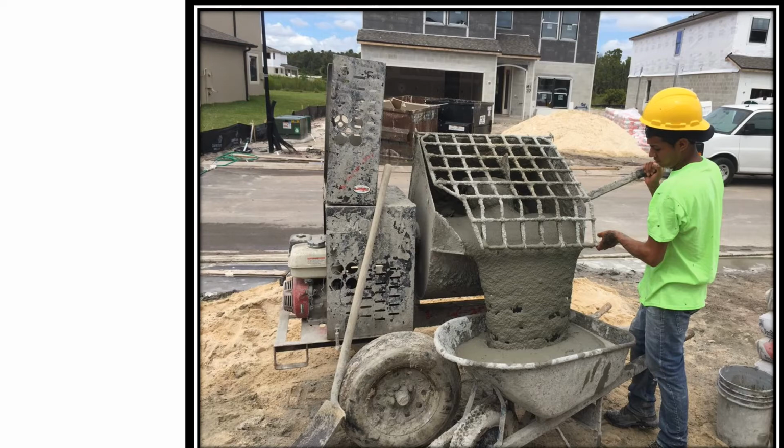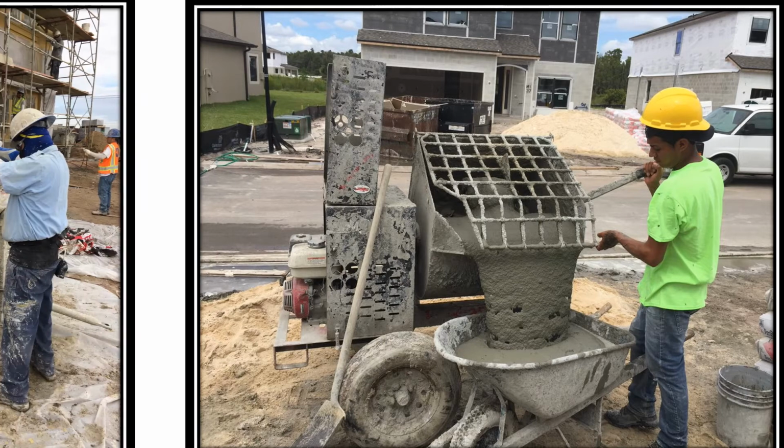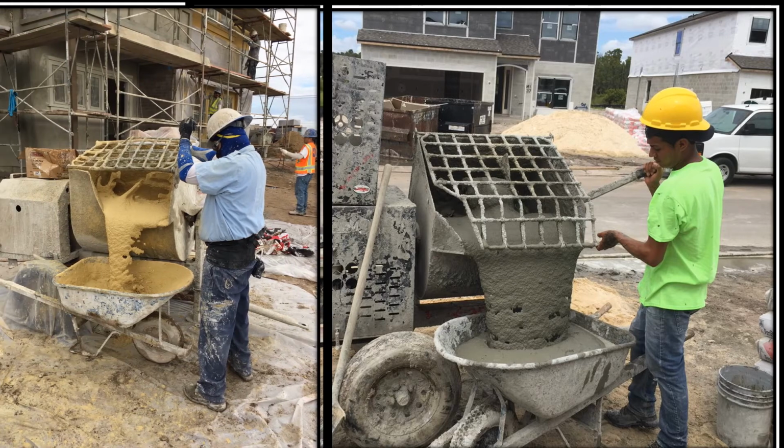However, several factors can alter that preference, and there is no correct amount of water to add or not add to be code compliant. It is strictly a job-by-job decision. The weather, method of application, and other factors all play a role in the consistency of the cement plaster base coat. The same can be said of cement finish coats. The texture may dictate the consistency as well as the substrate the finish is being applied to.